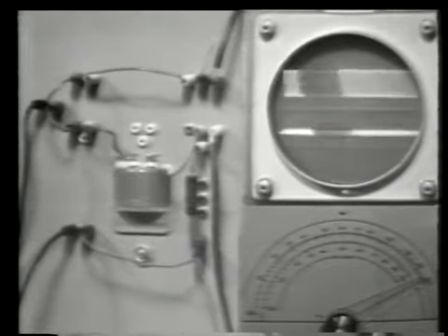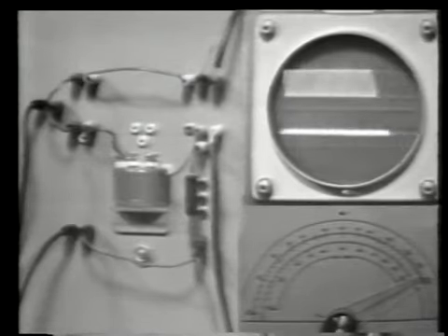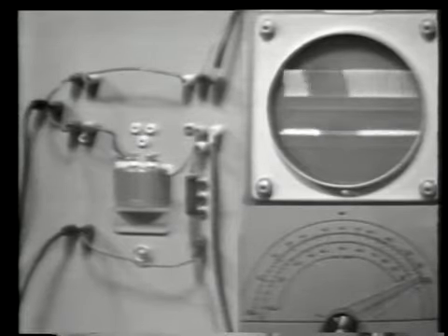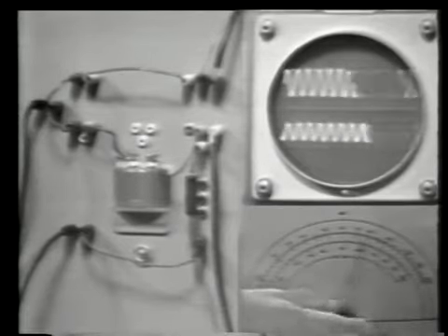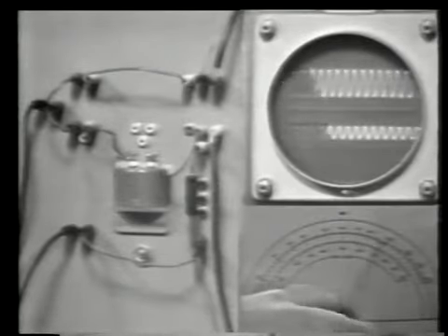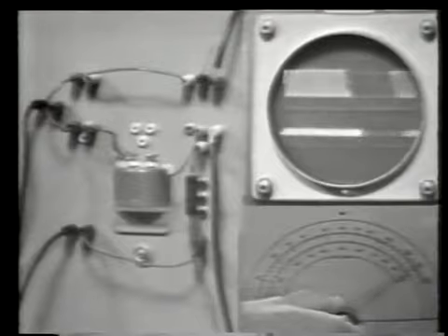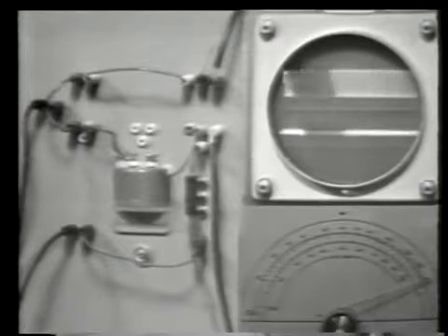With a 10 Henry inductor and a 0.01 microfarad capacitor as my filter components, I'm passing all frequencies from about 1 hertz on up to about 600 hertz, on up to about this point. But those frequencies above 600 hertz are not getting through. They're being rejected by our filter circuit.